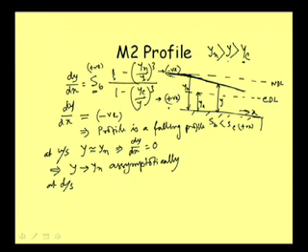But at the downstream point, what will happen as it is coming down? So y is approximately equal to yc. Why am I writing approximately? Because if I write y equal to yc, that is the critical depth, and then we are on the critical depth point, we are not on the gradually varied flow part. Here the flow should vary. So I am writing y is approaching yc.